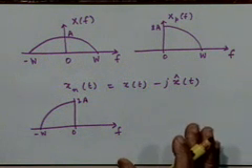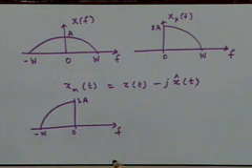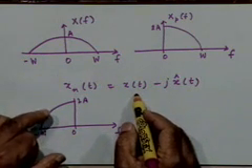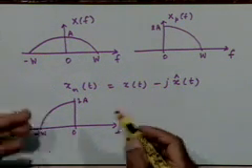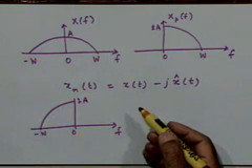So you see a direct analogy between what we are doing here and what we are already used to when we try to represent a sinusoid as a real part of a complex exponential, right? So again here also the signal of interest, which is a real signal, is a real part of either xp(t) or xn(t), right? The same relationship holds, a very similar relationship. So the development is absolutely parallel to what you already use very frequently in the context of sinusoids. Only thing is now you can use it in the context of an arbitrary signal, right?